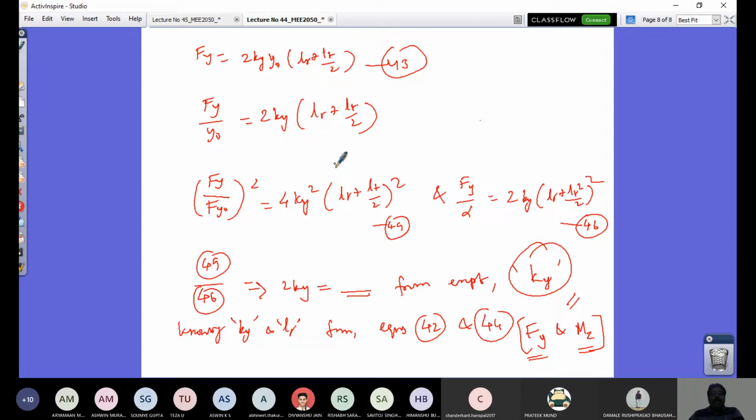It is pure longitudinal slip. We studied the physics behind the tread band model, which is an elastic model, and derived an expression of longitudinal tractive force versus slip, or braking effort versus skid. That is a purely longitudinal model.